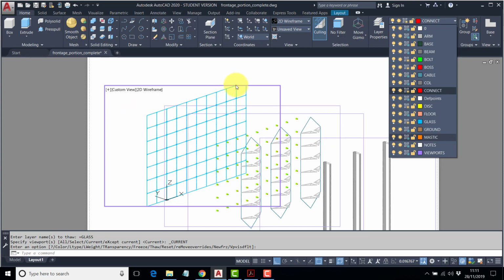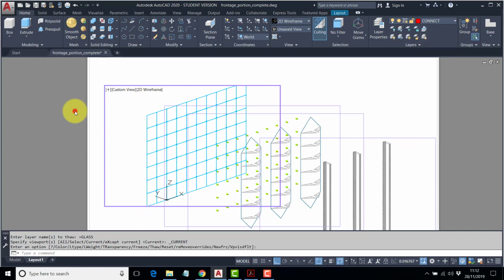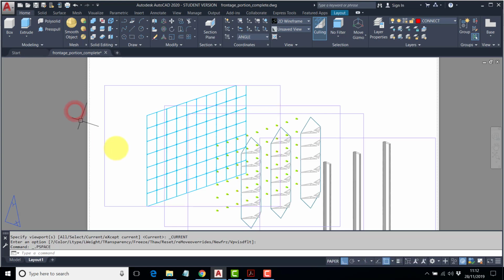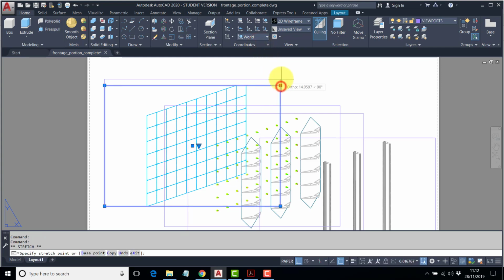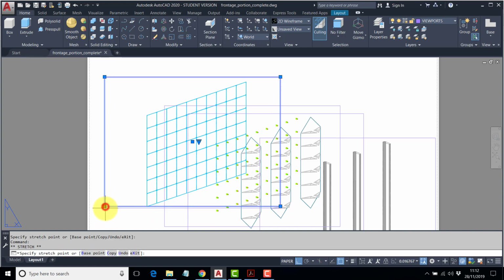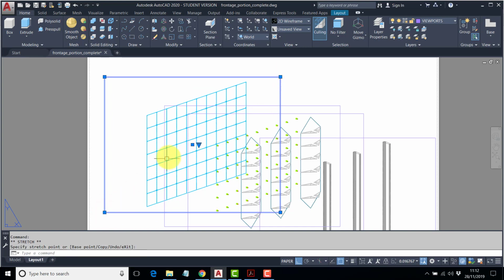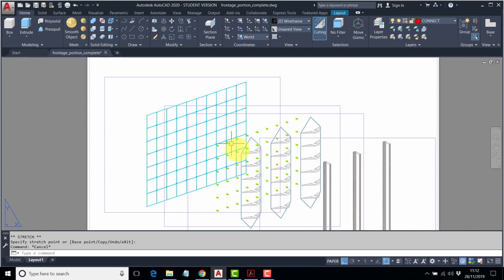You can see on this viewport it's just clipping the very top of the glass there, so we need the viewport, this back one, to be a little bit bigger. So double click outside, we need to go back to the world coordinate system, and then we can adjust the height of the viewport. Okay, maybe just a little bit down here so it's a bit bigger. Maybe a bit too much of an overlap happening here. I think we'll move this viewport back a bit more.